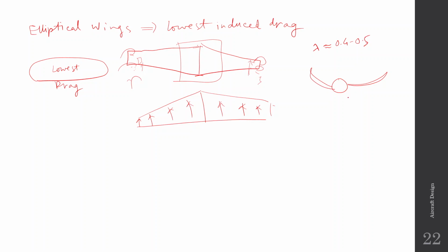Even when you fly in commercial aircraft, the wings do bend up a little bit, because the wings are carrying the weight of the aircraft. So if your tips produce a lot of lift, then the bending will be more. On the other hand, if the root produces more lift and the tips produce lesser lift, then the bending will be lesser.